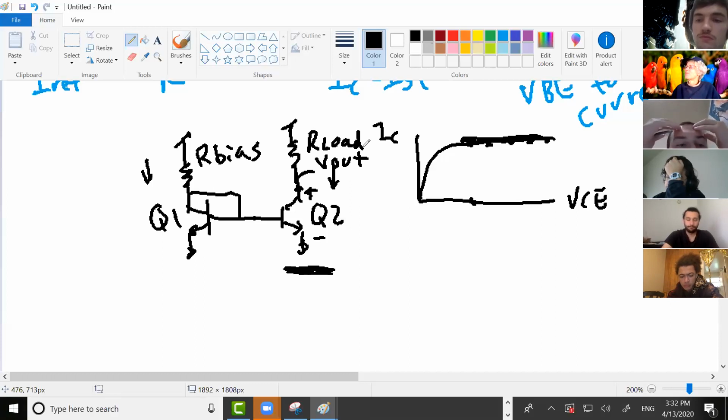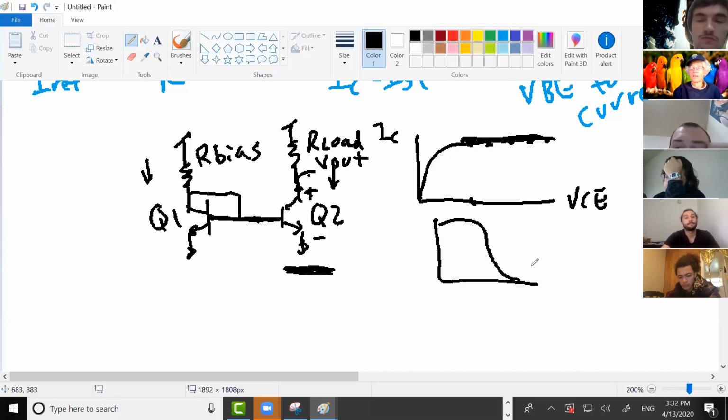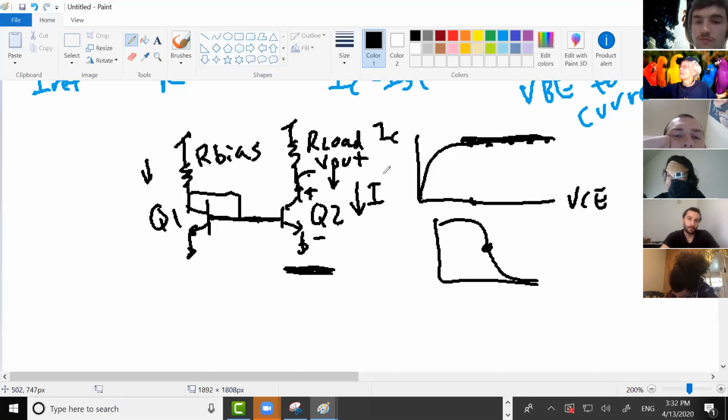If you're making an amplifier, you probably want to amplify something. And right now, all we've done is set a DC voltage. So V out will sit kind of in the middle of the VTC. All we've done so far is set a default current through our amplifier, but we're not amplifying anything. So this is actually not this week. Next week, you'll see this in lab. So this is jumping ahead. Without seeing the whole story, this biasing seemed weird to me when I learned it. So let me give you like 2 weeks ahead here.